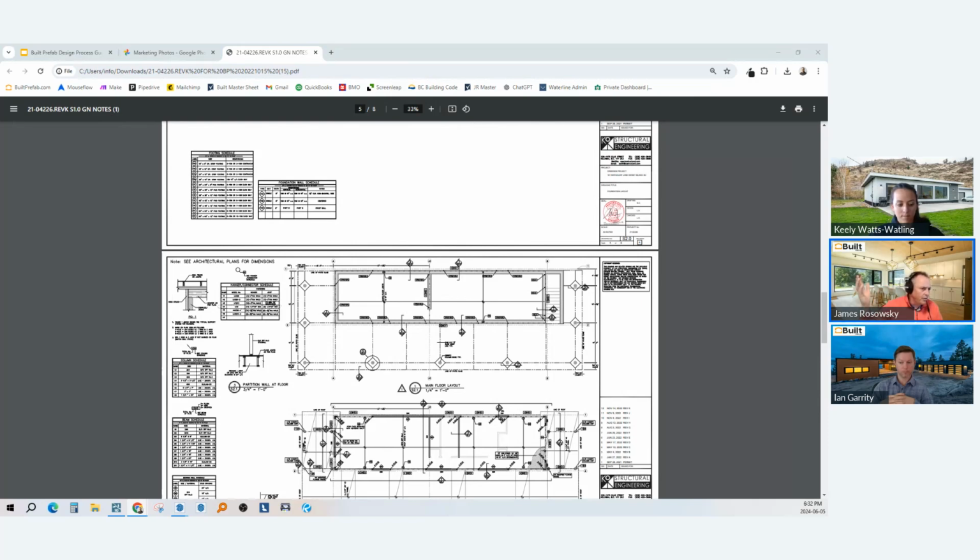Can the floor support the weight of a 7-foot grand piano? Absolutely. The way we build every floor is probably a little bit overboard, but we feel like you walk on it every day, so it better be great. So that's a TGI rim joist with our TGIs in between, and then we do 3/4 inch sheathing. It's super solid.